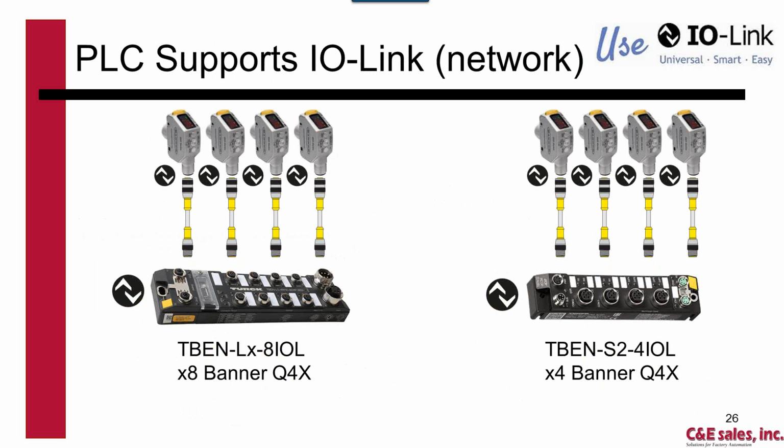So here's another use for IOLink. The whole notion of IOLink, in addition to simple sensor replacement, was for you to be able to take an analog value, RFID information, or an encoder value, it doesn't matter what the sensor type was, and bring it back to a common master module, an IOLink master, and send that back to the PLC either over a network such as Profinet or Ethernet IP or Profibus or any number of networks, even ASI, AS interface. Not only could you do that, but even if you had an IOLink master module residing in the local CPU rack, could you also do that?